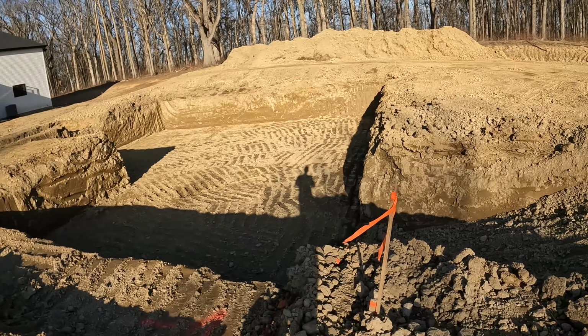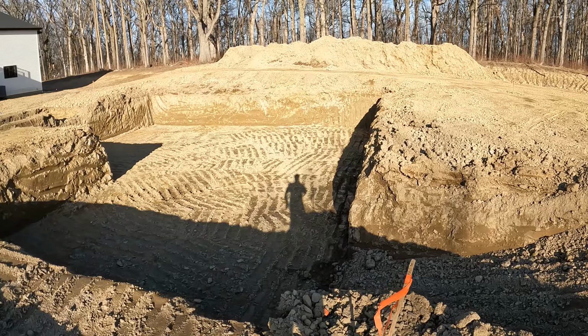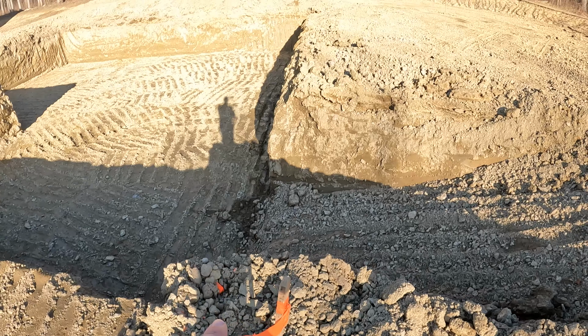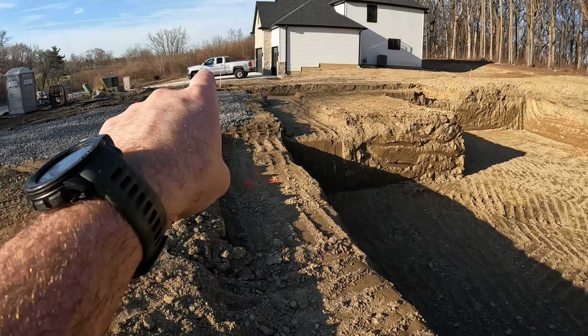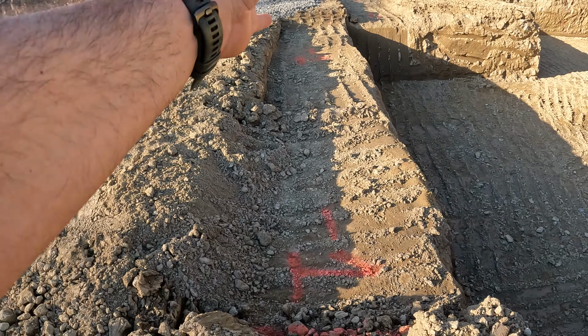This now is what we're left with. And these are the stakes that you guys saw back when this was snow covered and I was bundled up. You'll see that we still have them in place. You'll see our flag down there, one over there, one there, and our one here. So what they do is they'll take this and create a square box. And then they take all of their measurements for the footing locations, and then they mark them all out on the ground.